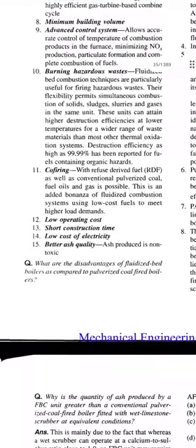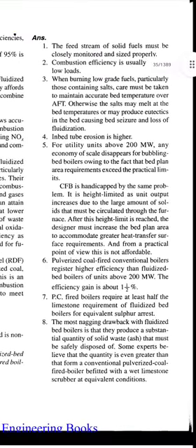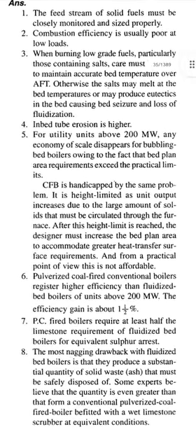So this is the question: what are the disadvantages of fluidized bed boilers as compared to pulverized coal-fired boilers? Answer is: the feed stream of solid fuels must be closely monitored and sized properly. Combustion efficiency is usually poor at low loads.